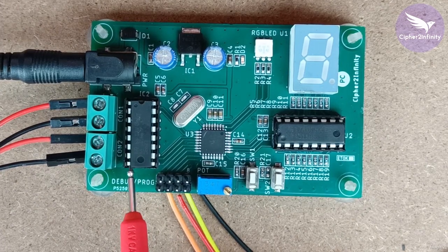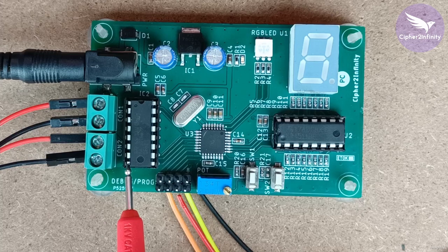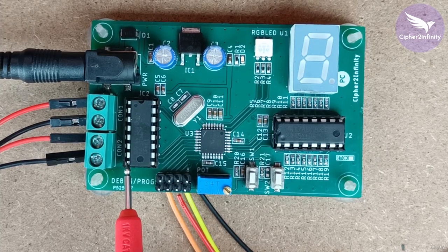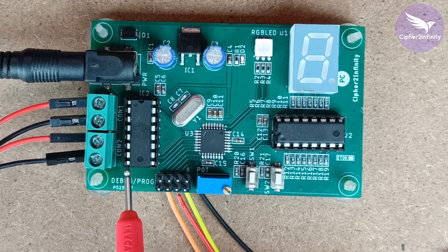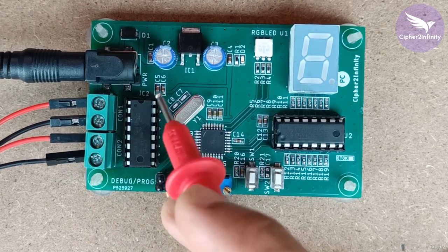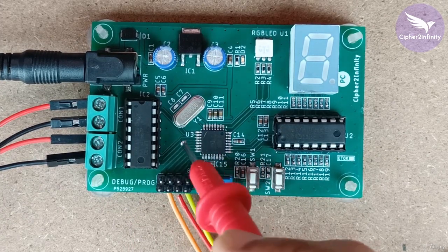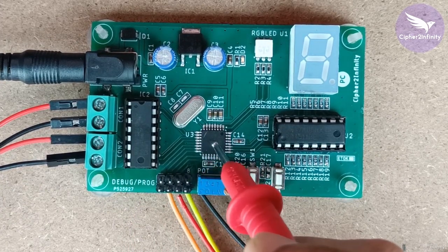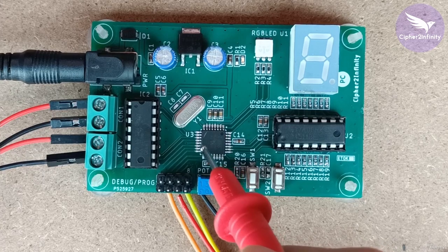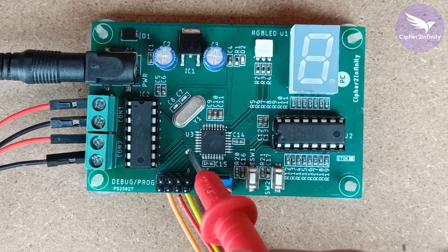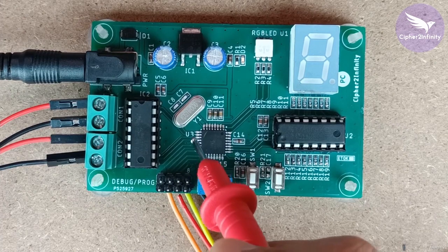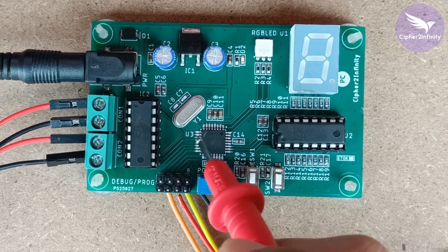So these things should come to your mind when there is no +12 volt at this point, or power supply voltage at this particular point, okay. So once you are sure that you are getting 12 volt here and plus 5 volt is available here, then you have to check the controller side. Okay, you have to check whether the controller is producing the control signals on the appropriate pins or not. Okay, so that you will have to check on the controller side.